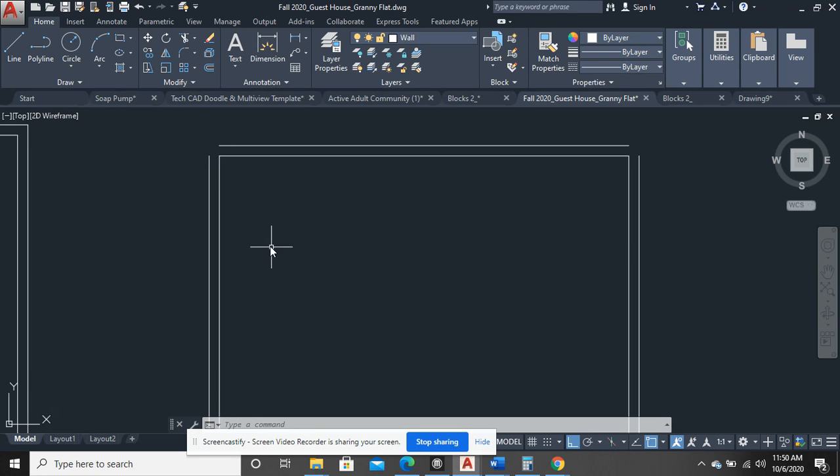Now here's a little trick, and I use this all the time in architecture. This tool under your trim, to the left of explode, is called fillet. Usually that means a round edge. It's rounding over an edge. But if you click radius and you type in 0 and hit enter, now there is no radius. So if I click this line and this line, it fills it in at a 90-degree angle. So real handy and real fast to do that.